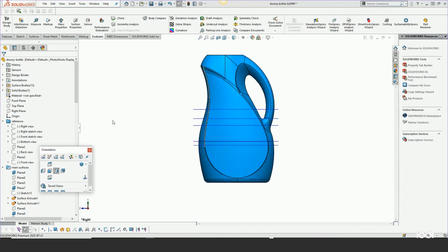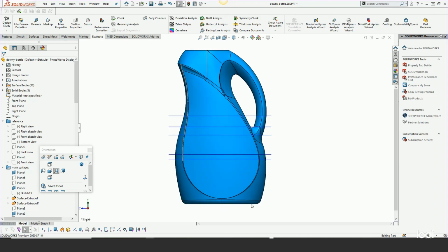You can do it with some add-on products, is to do a subdivisional surface model. Subdivisional surface models are really good at this kind of shape because it's a completely different paradigm of starting off with primitives and then pulling shapes or pulling nodes on that subdivisional surface to divide it and to work from a soft morphic form into more definitive form.